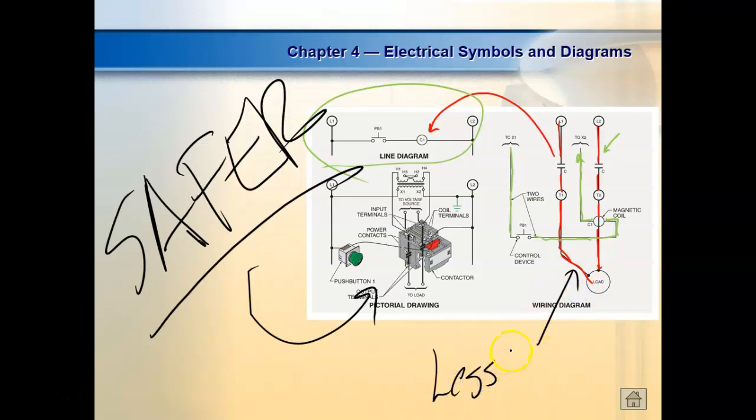Less current to produce the power, which means I can use smaller wires. I can use smaller fuses, right? You understand? So high voltage is not more efficient. High voltage is cheaper to install, and it allows us to run smaller conductors, which means they're easier to manage. So right now, if your electric water heater was running off 120, the conductors going out there would have to be at least twice the size, which means they could not run them through the wall anymore, right? And they would be a lot harder to handle. They would not be as flexible.